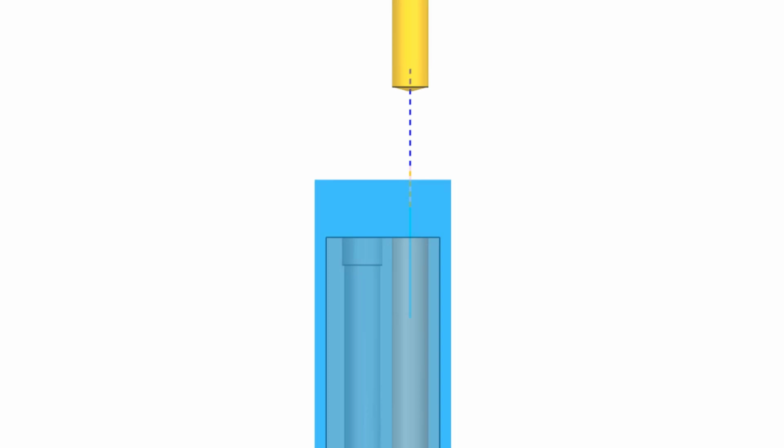The control point used by the initial drilling operation can now be used by subsequent operations in the sequence, allowing the tool to move to the same clearance position above the IPW for each operation and preventing a rapid movement into the previously drilled hole. As a result, you can achieve better control for entry into the hole, improve machining quality, and reduce tool wear.